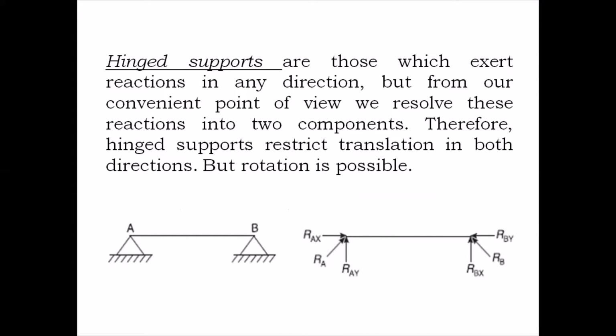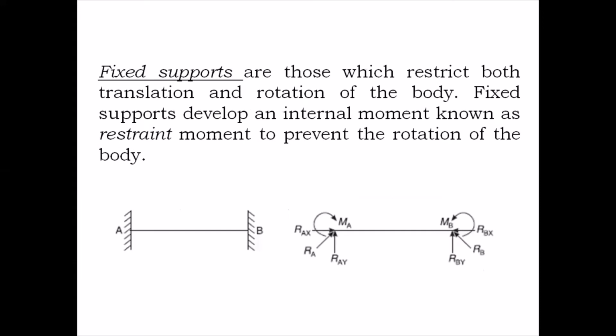whereas in the third support, that is fixed support, we have a support wherein translation in both directions is restricted along with rotation of the body.